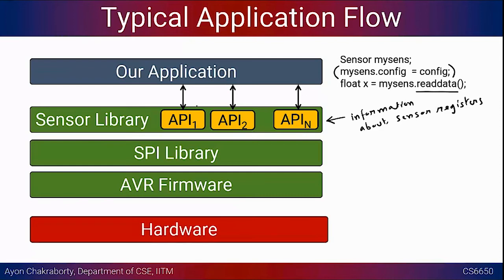The underlying communication protocol here is just SPI, and that does not mean you can always communicate data, because the sensor has to make sense of it, right? If you send a certain query, the sensor needs to understand what you are asking for. So for implementing that, you also need to consult that particular sensor library.